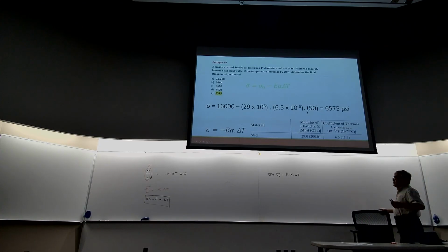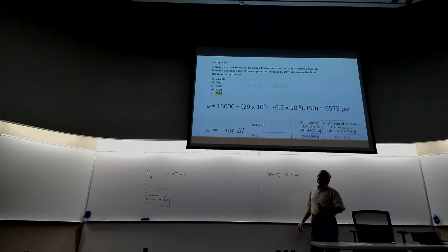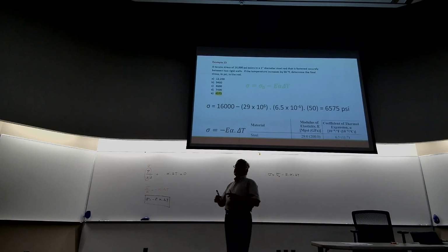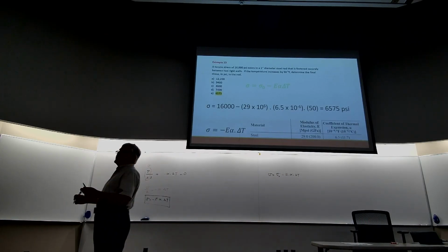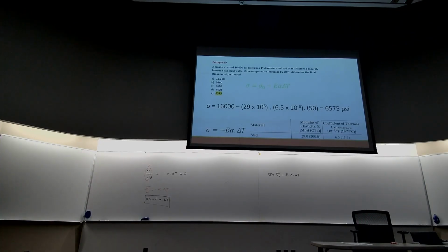The units automatically work out, and you get the final result in psi. If you want to, you can write them out and cross out the units, but if you stay with standard units everywhere, inches, not feet, psi for everything, E, etc., then you get the result in automatic, standard units for sigma, which is psi.